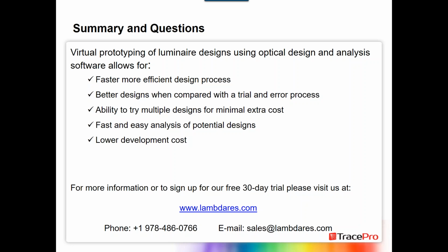Yeah, and we have a customer who is fantastic at making silicone optics, and they've had amazing efficiencies out of making these lenses, but they've also spent years creating the process that makes really, really smooth optics. Because if you turn on your optic in a dark room and it glows all over the place, you've got a lot of surface roughness, and unless you eliminate that and get down to an SP1 type level on those surfaces, you're going to lose a lot of light in these particular optics.